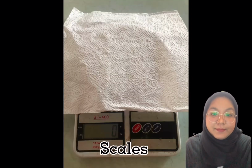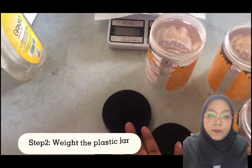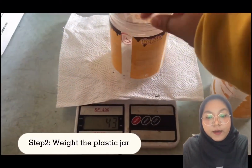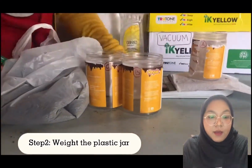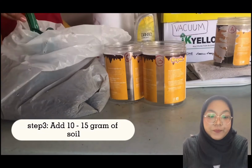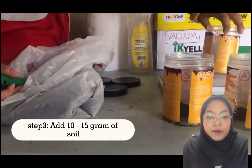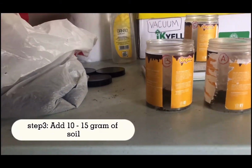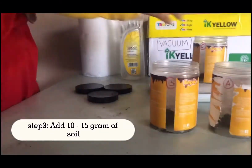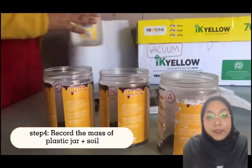scale. For step number 1, first we need to sketch the diagram of how I will conduct my experiment. Step number 2, weigh the plastic jar and record it. Step number 3, add 10 to 50 grams of soil into the jar and record. Step number 4, record the mass of plastic jar plus soil.